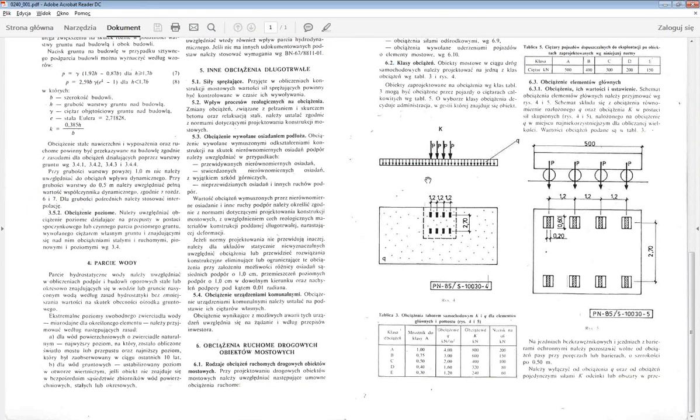So we have so-called heavy vehicle. This name is K vehicle, and here we have a scheme of this vehicle. It's 4 axles, 8 wheels, and weight of our vehicle class 8 is the heaviest vehicle, is 800 kilonewtons. We also calculate so-called dynamic factors.